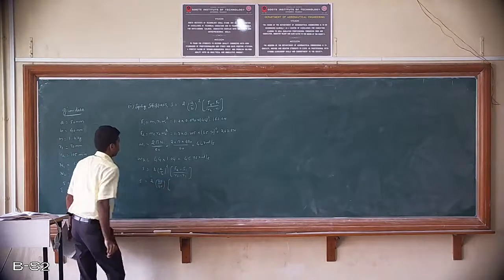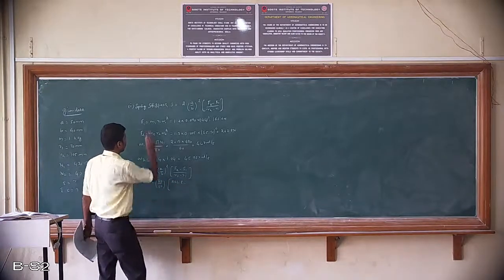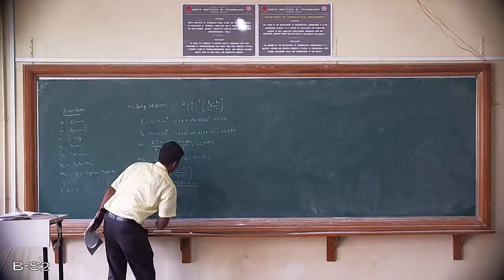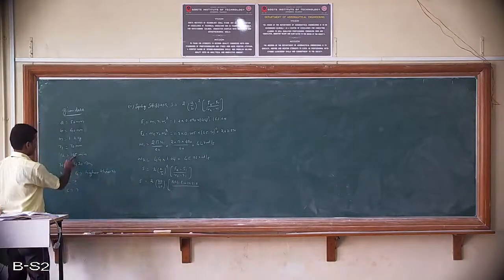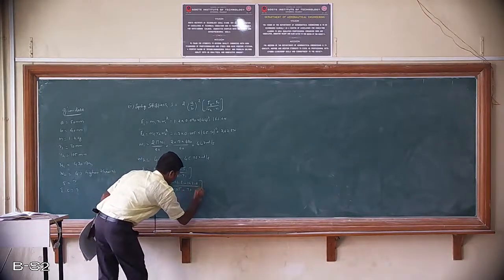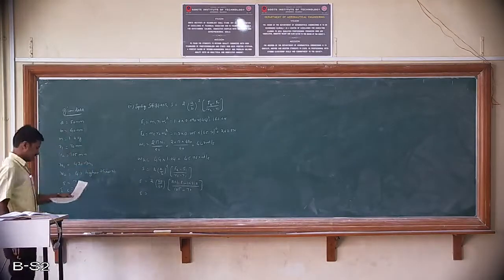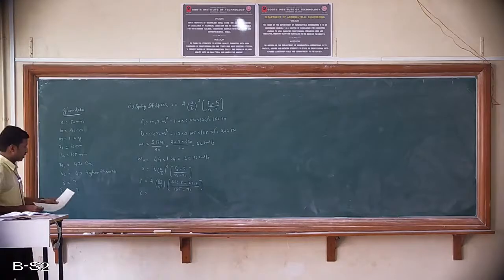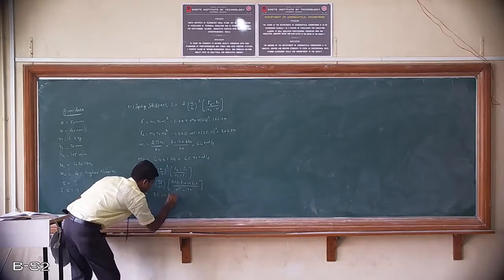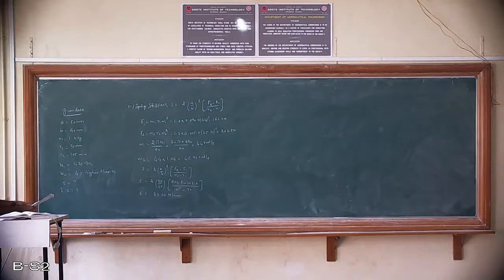F2 is 263.8 minus F1 is 162.6, divided by R2 and R1, where R2 is 105 and R1 is 70. With the help of calculator, substitute all the values and get the value for S. The value for S is 23.14 Newton per mm. So this is the value for spring constant or spring stiffness.